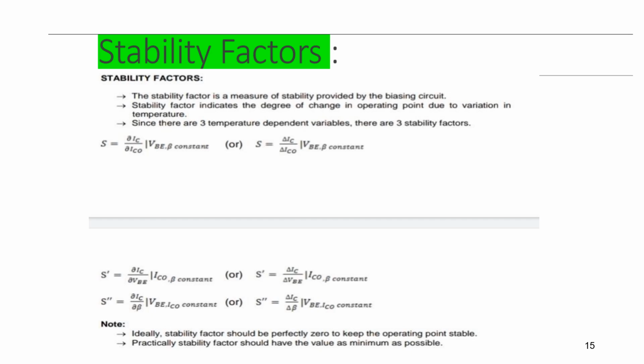So these are the stability factors used to fix the stability of the circuit. For a circuit, which one has the lower stability factor? Stability factor means the change: how much IC changes. IC is one of the operating point quantities; VCE comma IC is the quiescent point. IC should not change, because if IC changes, the Q point changes and we will get a distorted output. Whatever parameter changes, if IC is constant, the Q point will be constant, and we will get a faithful output.